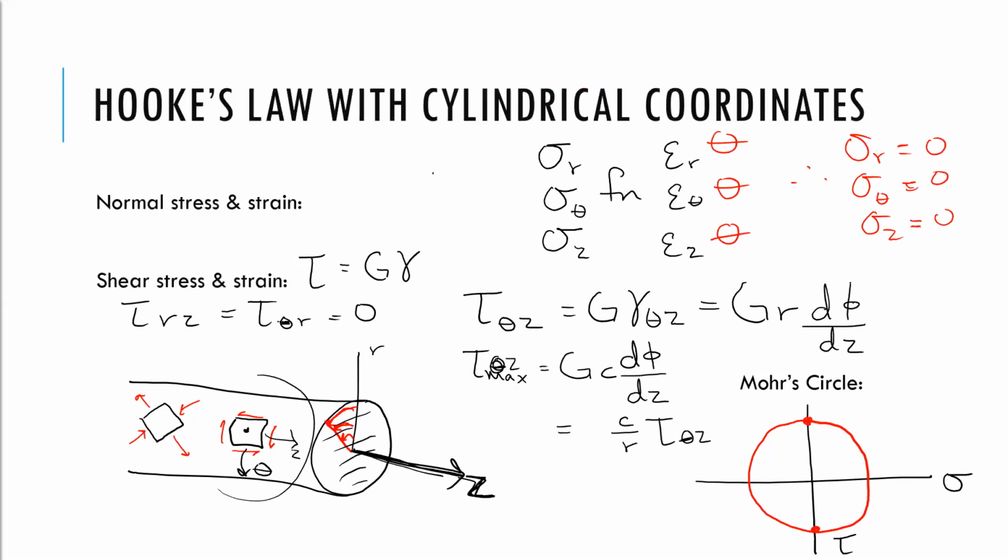And then it's the opposite on the other end. So on the end of this rod that's pointing in the negative Z direction, your positive torque is with your thumb pointing in the negative Z direction. So really, it's always pointing away from that member for your positive torque. And positive torque is going to give you positive shear.